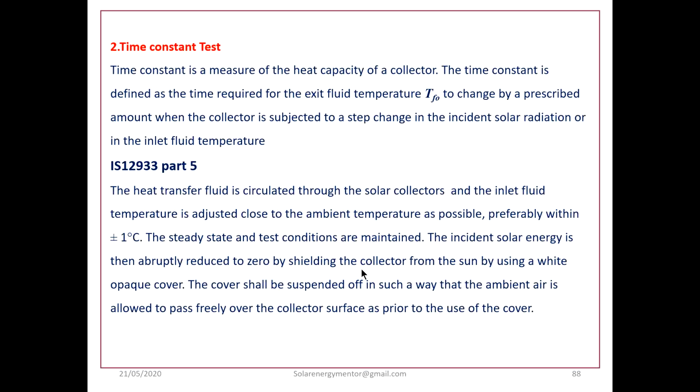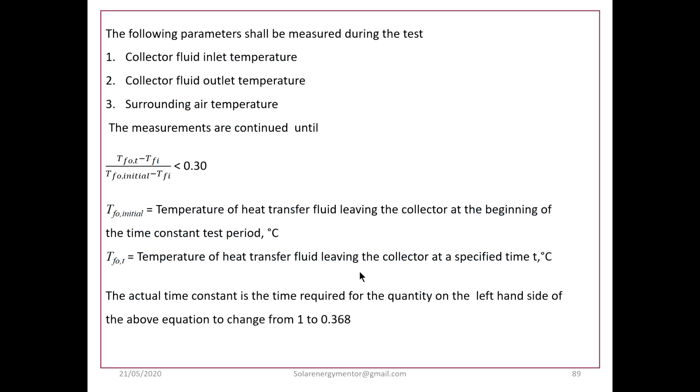The plastic cover should not just be put on the collector so that airflow is restricted. No, the cover shall be suspended in such a way that the ambient air is allowed to pass freely over the collector as prior to the use of the cover. So the cover has to be just held at a height over the collector. The collector is needed to be shaded. In this condition, the following parameters shall be measured during the test.